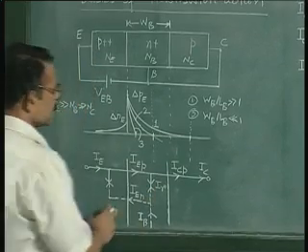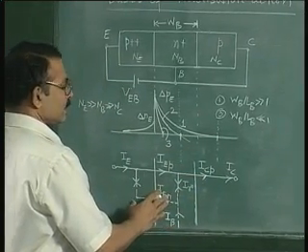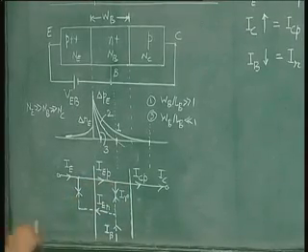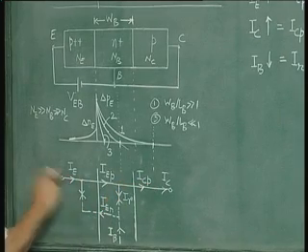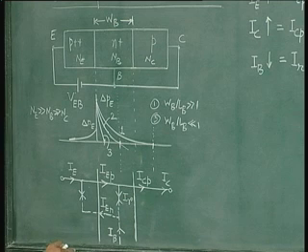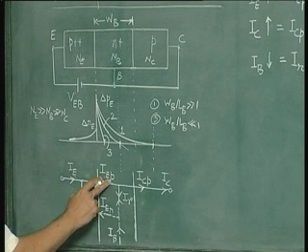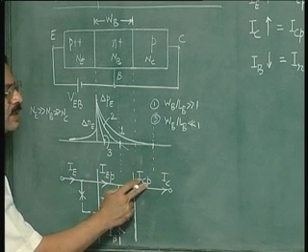So because of this particular condition for the various currents, it is of interest to know what is the ratio of the collector current to the emitter current. Now to write this, we should recognize that part of the emitter current is the hole current, and part of this hole current is this hole current which is reaching the collector.